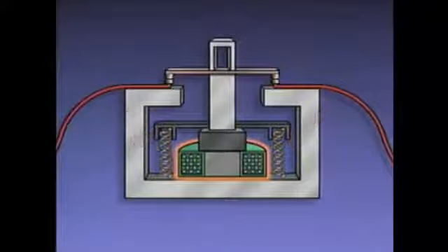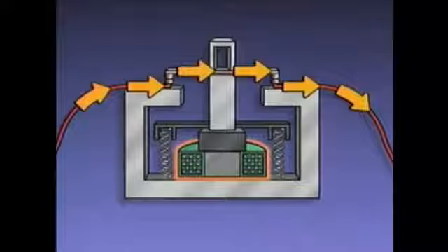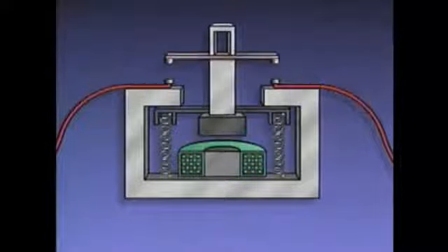When the contacts close, a complete path for current flow is established through the controller to the motor. When the M coil is de-energized, the electromagnetic field is removed, and the springs push the armature back to its original position, separating the two contacts.